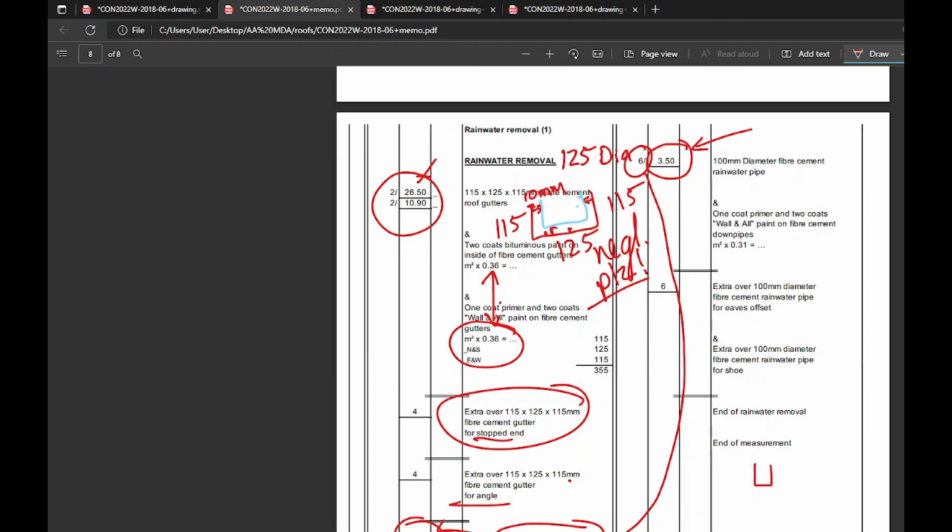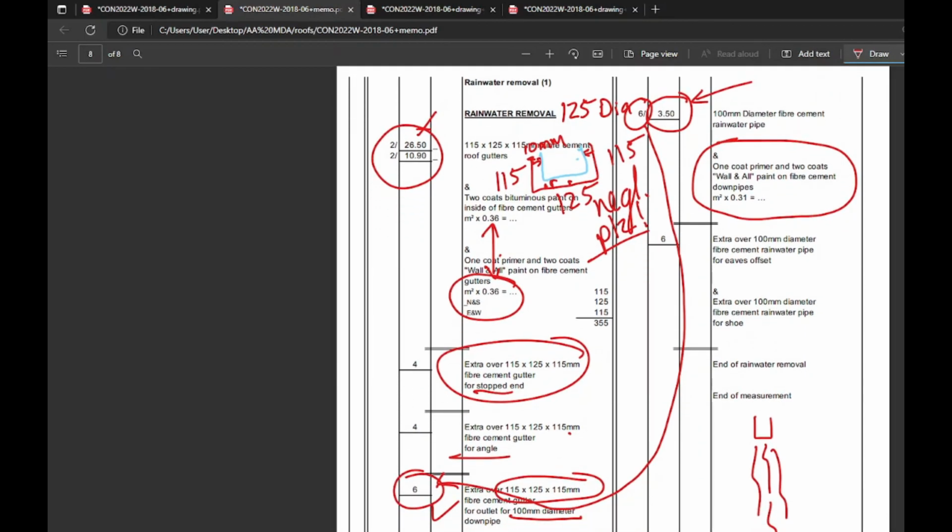You can't have an outlet and then water just sort of runs out the side of your gutter. I mean, you probably could do that, I don't think it's a good idea. And at the same time, you only coat the outside of your downpipe. For the sake of completeness, you probably could coat the inside of your downpipe, but we do not cover it in the course. If you want to be creative, maybe you just pour bituminous paint down your downpipe until it comes out the other end into another bucket, and then you let that dry, and your downpipe is now bitumen coated on the inside. That's pretty easy, I don't think it's too difficult to pull off. But anyway, you just coat the outside as per spec.